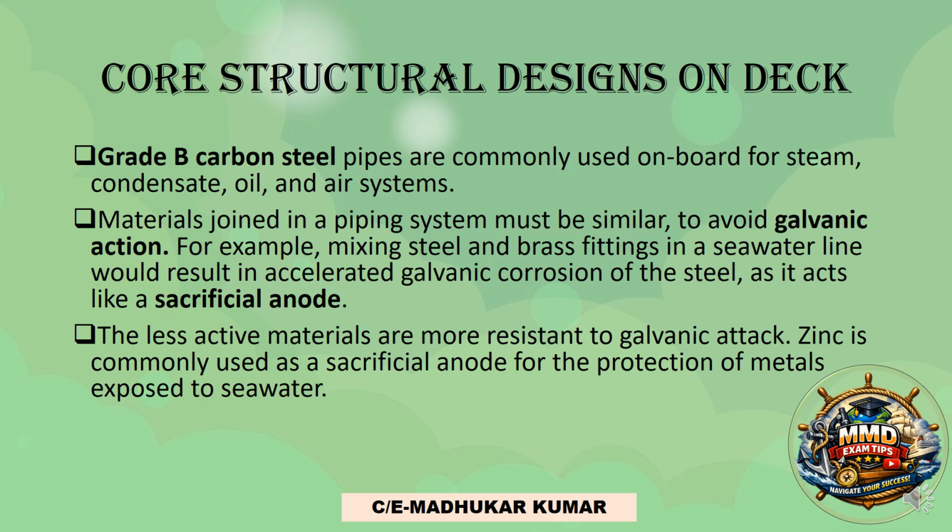basically core structural design on deck. Okay, so when we talk about deck, generally grade B carbon steel is commonly used on board, basically on deck, especially on steam, condensate, oil and air systems which are passing through the deck. So this is grade B carbon steel.